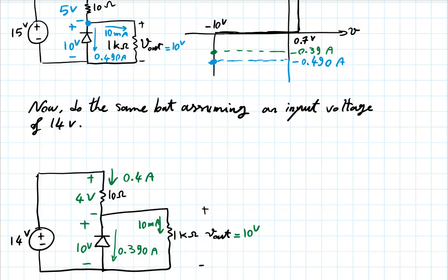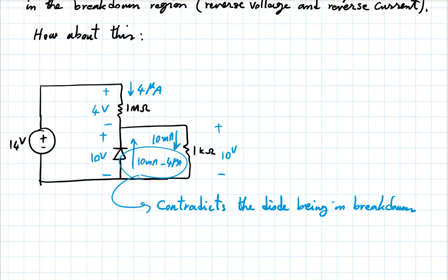Right? But you see that there are some things to be considered. For instance, what is the value of this resistor? If it was 10 ohms, it worked. If it was 1 mega ohm, it didn't. So go through the circuit again. Like I said, play with a few different values of input and those resistors to see how things change. This is the essence of regulator design.